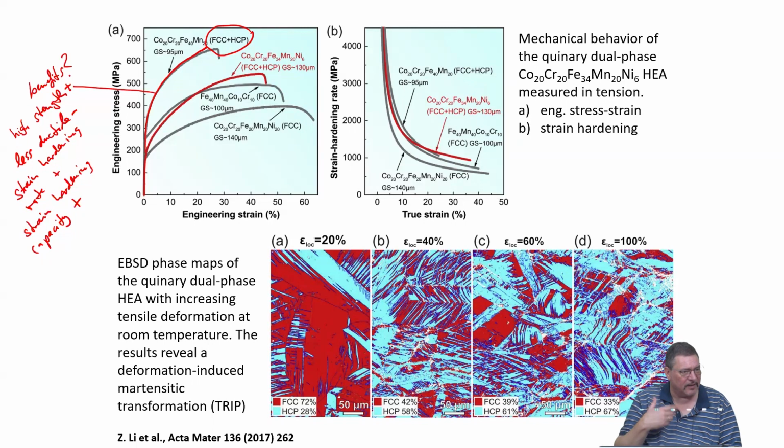And this is lying then in the microstructure. And in this case, there is also a TRIP effect because the martensite is formed during the deformation. And this is what's adding. Why is actually a phase formation helping?